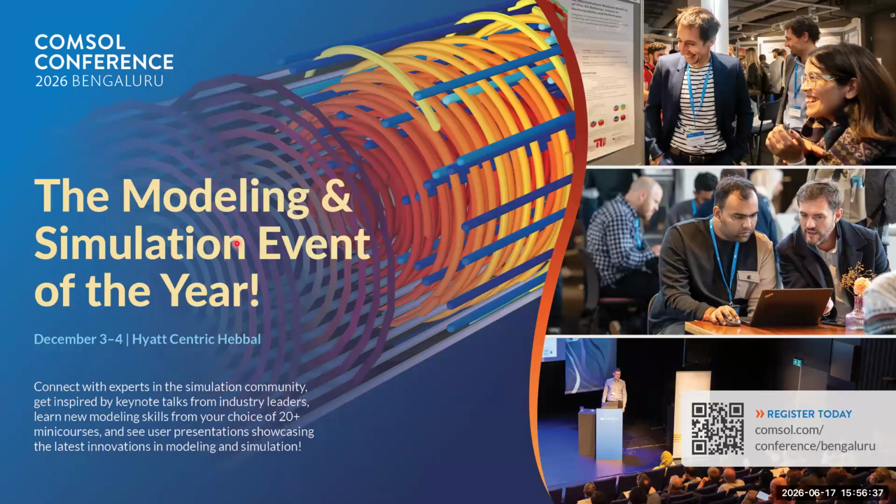We have a few interesting questions here, Kavita. The first one is, can we couple a circuit with motor modeling? Yes, you can couple an electrical circuit with motor modeling as well. Say, for example, if you want to connect your motor with an inverter or any other electrical circuit, you can couple it with an external electrical circuit. COMSOL has an interface called the electrical circuit interface, so you can couple your finite element model with the electrical circuit interface.